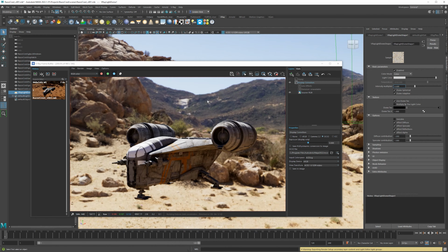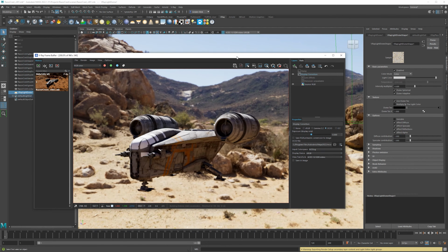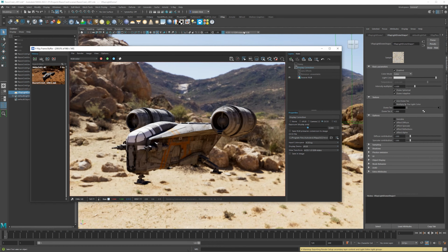Now, something that is really, really useful about the new version of Maya is that it uses ACES color. So ACES color is a color profile system that allows interchange between lots of different types of cameras. So really, really briefly, I want to explain this in more depth, but it can get really technical. When you're doing color corrections for film and you have lots of different cameras, every camera interprets color slightly differently. So if you're trying to take two shots and make them look the same, like as if they were shot on the same camera, it can actually be a little bit tricky to do. So ACES originally was set up as a way